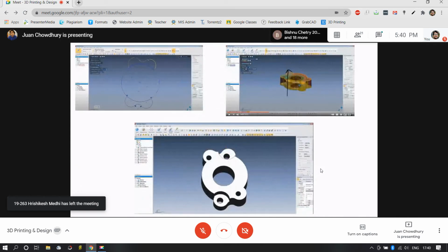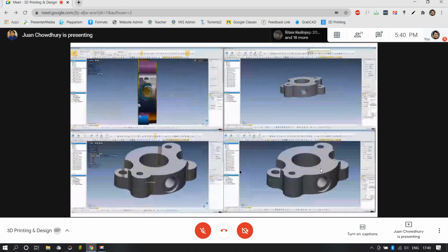While extruding the system, often the information about the holes gets lost. Then you have to select the holes individually as they will be highlighted in the texture. Okay, and then go to extrude cut as you do in solid modeling software. So once you have done the extrude cut, all these geometrical surfaces will appear, which will be seemingly relevant to the actual model.